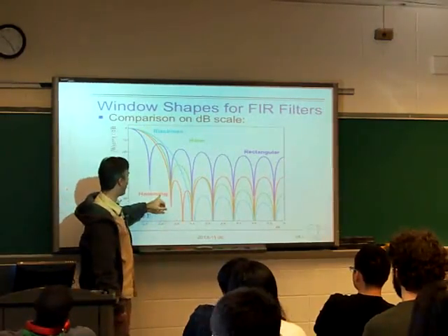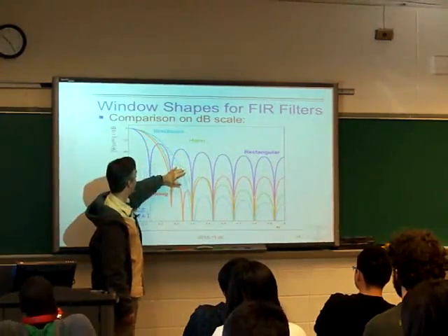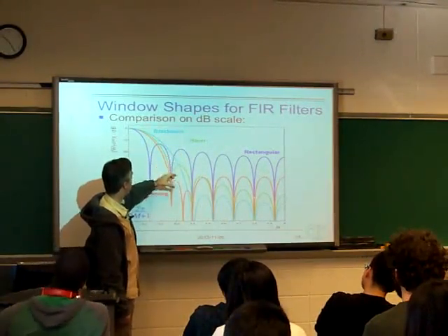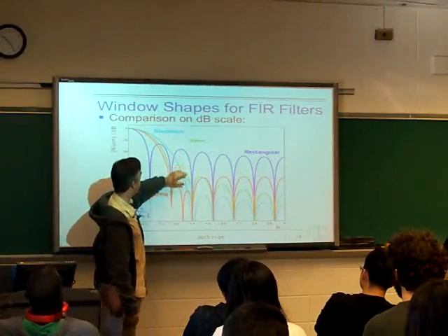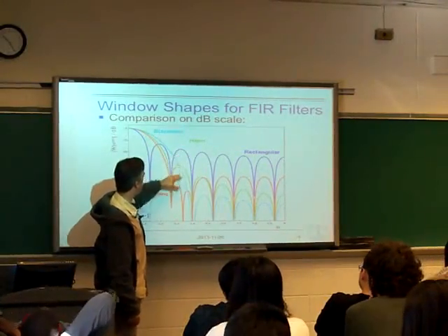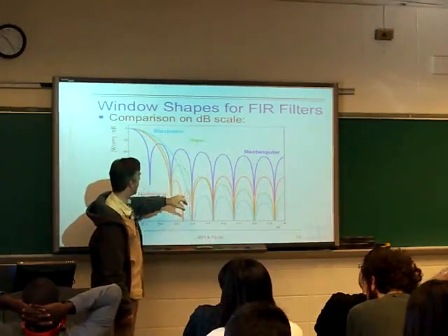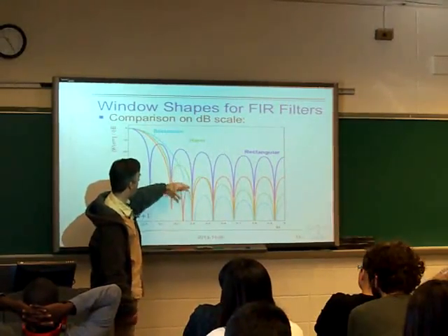So the Hamming window is this thing where we basically take the sum of the rectangular and the Hann in such a way that we cancel out this first lobe of the green with some of the blue. And so we have this extra 0 in here where they exactly cancel. And so this first lobe is greatly reduced.